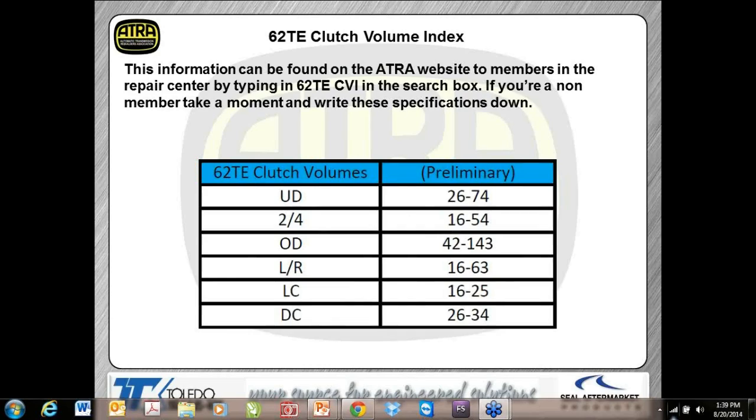4th gear upshift, the normal overdrive position, underdrive clutch and overdrive clutch are driving, and that's in the main case area, and the low clutch is holding, and the overrun clutch is holding in the compounder assembly. We go to 5th. We still have the overdrive and underdrive driving in the main case, and now we have the direct clutch driving in 5th gear in the compounder assembly. Last gear, 6th gear, overdrive clutch. Now the 2/4 clutch comes back on, the brake clutch, which is holding, and the direct clutch is driving. So there you have it. That's the power flow from reverse and from first gear all the way to 6, including 4th prime. So that's all 7 forward gears.